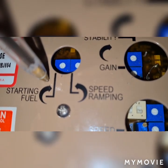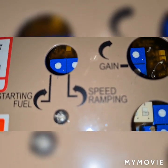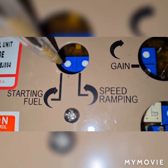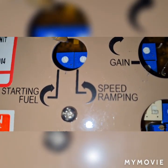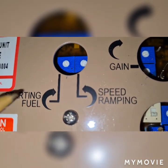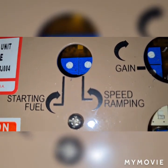So you will see the actuator begin to retract and the fuel going to your engine will be minimized, so you will be able to reduce the smoke and the RPM. Then gradually rotate this potentiometer in a clockwise direction. By rotating in a clockwise direction, you obtain the desired RPM value of 1,800 RPM as rated on your engine.